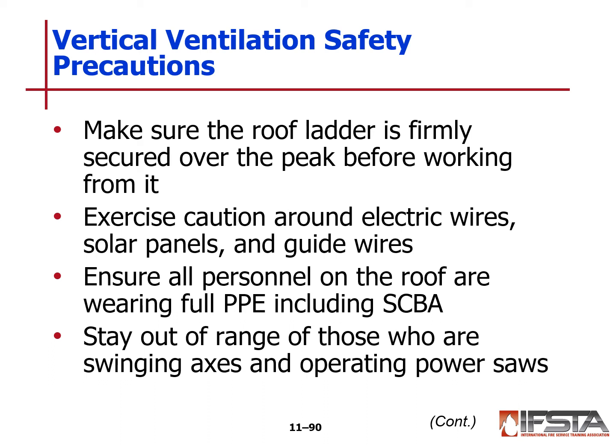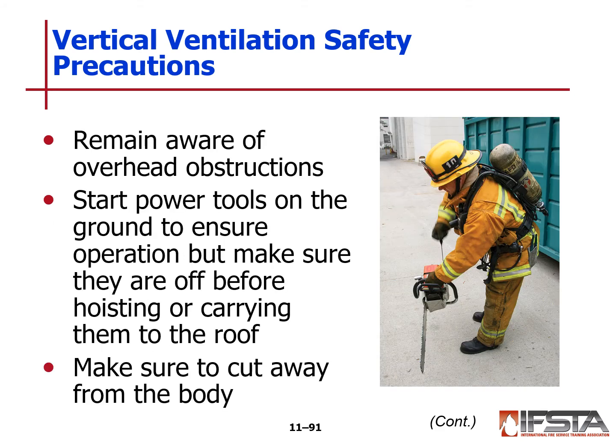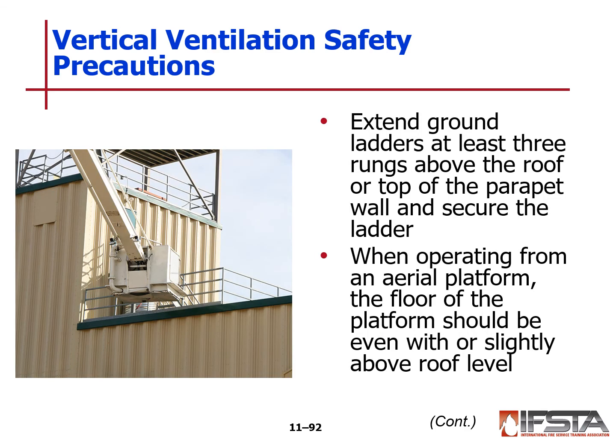Stay out of range of those who are swinging axes and or operating power saws. Remain aware of overhead obstructions. Be aware of where your service drops are, if they're overhead or coming in for the power. Start your power tools on the ground to ensure that they operate, and make sure they are turned off before hoisting or carrying them to the roof. So get them running, let them warm up, shut them down, carry them to the roof, and then we'll restart them. Make sure to cut away from your body, not towards your body.